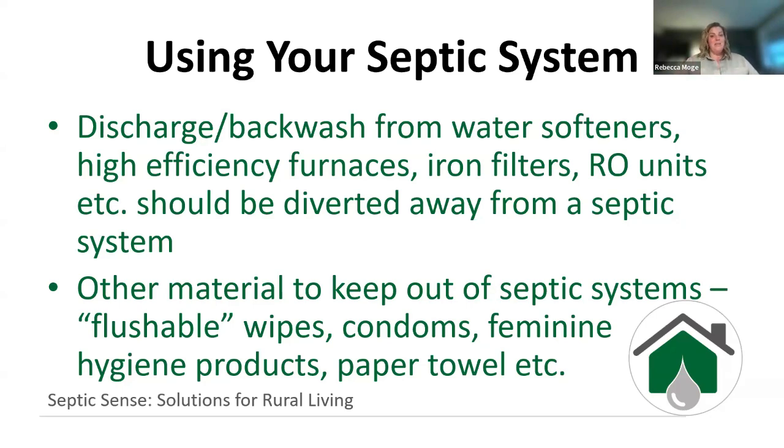And again, things to keep out of your septic system. Because it's called flushable, just because it goes down the toilet doesn't mean it should. It can be flushed, it's flushable, but it doesn't mean it should be. So any feminine products, paper towel, flushable wipes, condoms, things that should not be in your septic system.